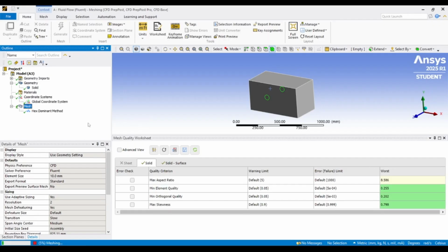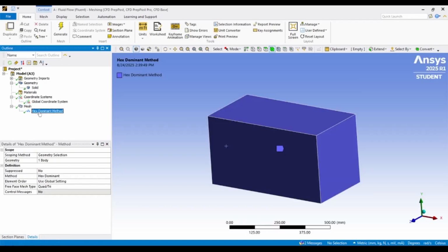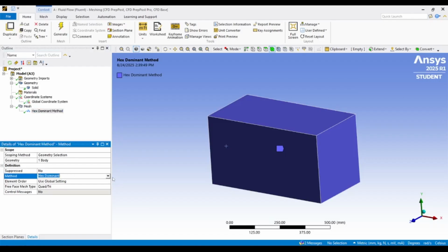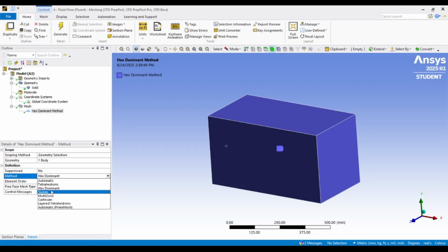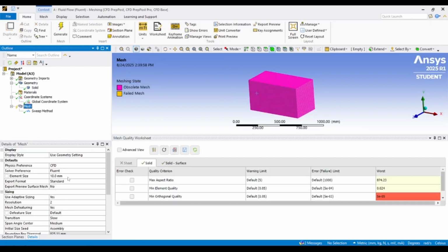Beyond this point, the boundary layer begins to lose momentum due to the adverse pressure gradient, and eventually the flow separates from the surface. This separation is responsible for the formation of the wake region behind the cylinder. In your Fluent results, you can visualize this pressure variation by plotting the pressure coefficient Cp along the cylinder's circumference.